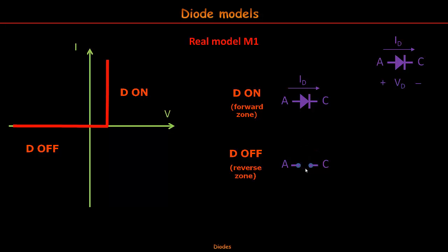An open circuit here. But now the forward bias zone must be represented by that forward voltage, and then the diode will be replaced by a voltage drop, exactly the same as the forward voltage or the barrier potential. While the diode is conducting current, the voltage falling between its terminals will be the forward one, from anode, higher voltage, to cathode, lower voltage.